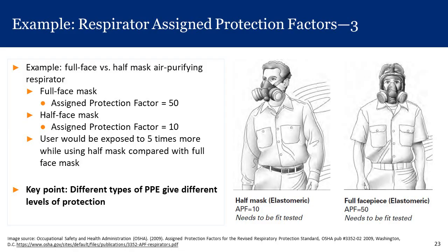Another example that I don't have here on the slide, but I should mention, this applies to gloves too. Whatever gloves you're wearing, they have to be impermeable to the chemical you're handling. If you're wearing gloves that are made of a material that can be dissolved by the solvent you're handling, that glove is not going to give you very much protection. You may end up dissolving the glove right off your hand, right? So we have to make sure when we use gloves that we use the right glove for the right chemical. We had an issue with a solvent that was widely used.